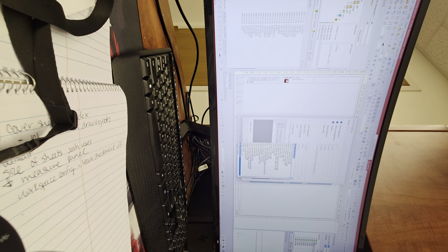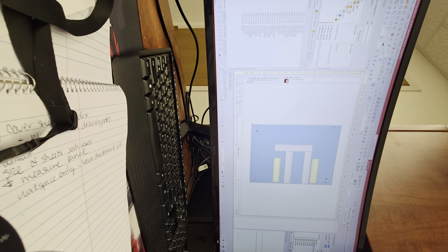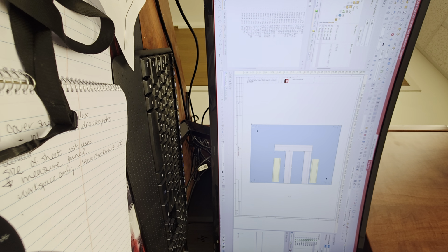Because you want to make sure that your wires are mimicking the flow, how they currently are in your project. If they just need to go from a top rail to the bottom rail, like your picture showed, then technically speaking you only need one duct between the two rails. Okay. One duct, just so the wires can go into the duct and then go left or right wherever they need to go, and then go down to the next rail. So let's just take your top rail and move it slightly up, just so we will have a space to put a component on.